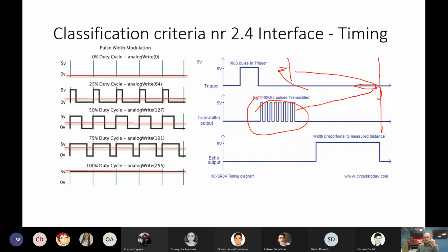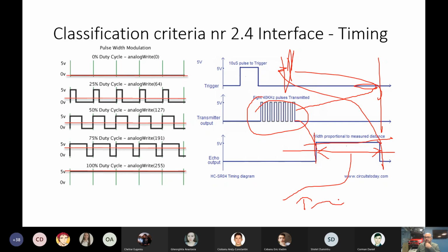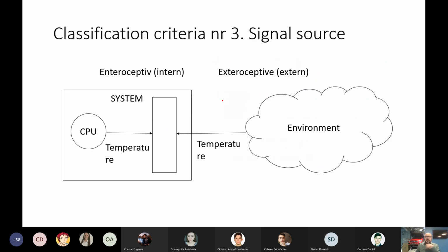Once it is sent, we have this trigger, this toggle of the signal, and when it reaches back the microphone, we toggle it back, and we have this signal on a wire. What we should do in the microcontroller to measure this value is measure the time, and from the time convert it into a value. How? We will see in one of the laboratory works maybe. So next.